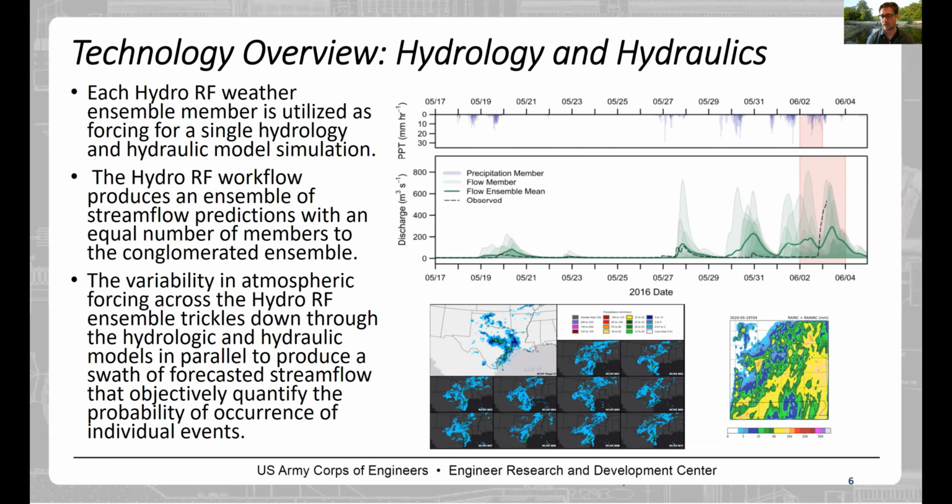So at a specific location over the next week or so, we can determine a forecast for each individual member. Since we have 10 different members in this case, we can start to create a probabilistic forecast. So we can look at the average of the forecast, or we can look at the 95th percentile or the 5th percentile to start to understand what's the probability of a flood at a certain area at a certain time.